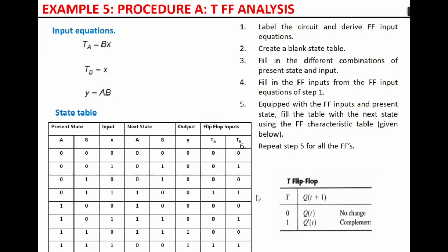Okay, A is 0, TA is 1. If TA is 1, it toggles, so you get 1. So you should have filled that for A and B using those. And then your table is here. In the exam, don't struggle and remove this and draw another table. No, we're not examining you on how to draw. Once you reach here, you know the state table consists of that, and that. Just leave it. Any question there?